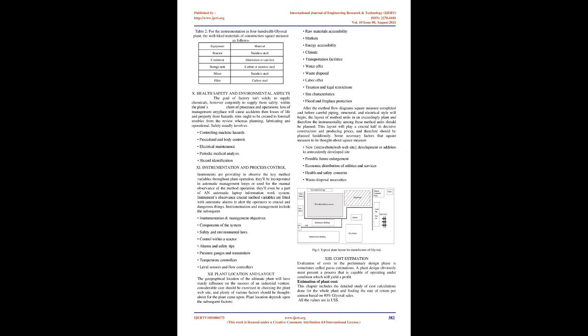Recirculating gas used as an agent and glycol solution coming into the reactor are in turn preheated by the heat generated during the reaction of glycol at the catalyst, and cooling of the reaction products is performed by their irrigation with cooled glyoxal solution in a zone lying immediately behind the catalyst layer and in a tubular two-sectional heat exchanger. In the lower section of that, glycol is heated, and in the higher section, the recirculating gas used as an agent is heated.